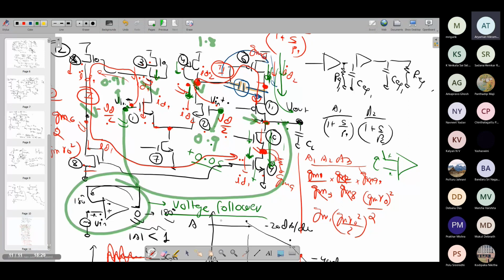Yes, sir. But if we are trying to design a general op-amp... In a general op-amp also you will have feedback. General op-amp means ultimately you will have some kind of feedback. Suppose you are putting in an inverting gain amplifier. What will you do? Rather than shorting it like this, you will put a resistor R1, R2 that will also establish DC bias. Let us draw that.